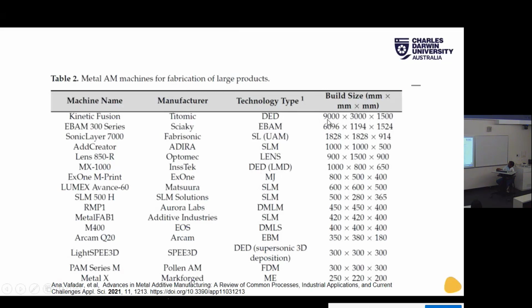It says it can go up to 9 meters, but that is done differently. The entire system of delivering the powder is put on a large-scale gantry crane, and then the powder is delivered using the same de Laval nozzle, a converging-diverging nozzle, and the part is produced.